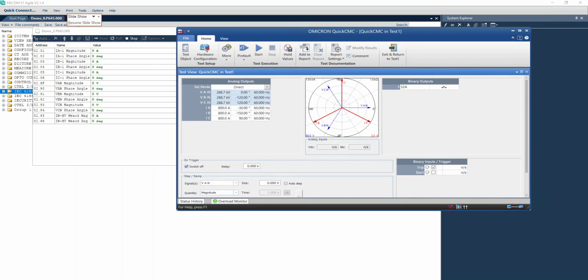To configure a GOOSE application, there are 3 steps. Prepare a GOOSE dataset, set up a GOOSE control block, and specify which IEDs are going to receive that GOOSE dataset. In this video, we will show how to configure the CMC 356 to publish a GOOSE message.